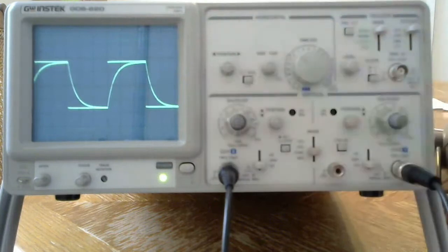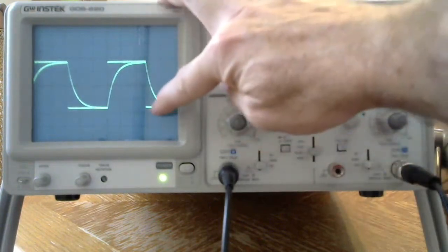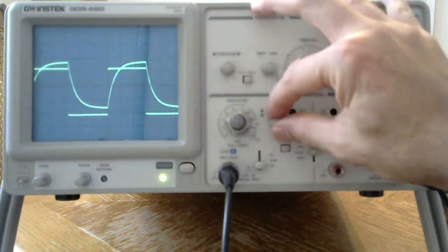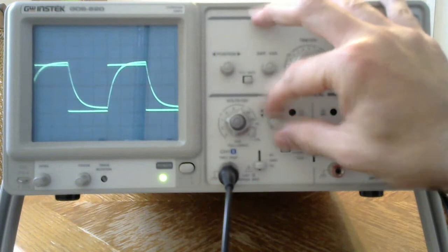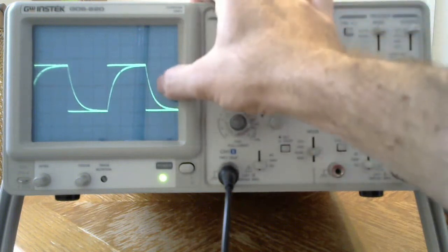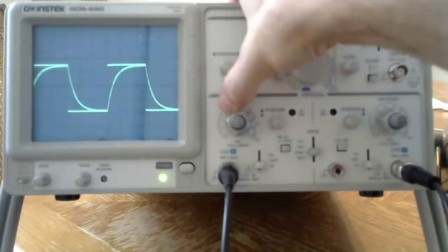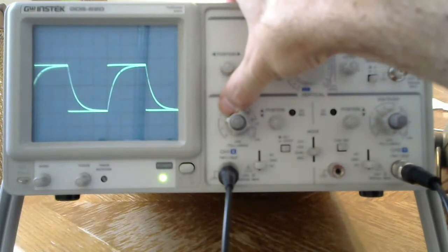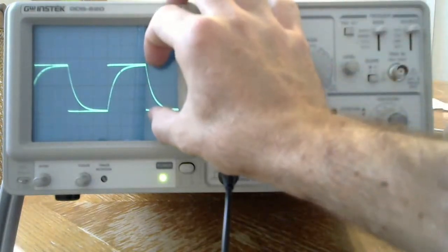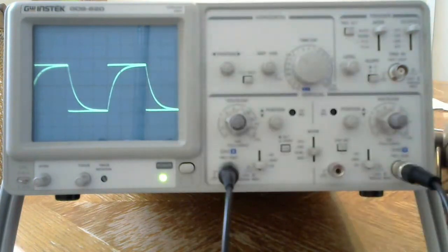Okay, so I'm going to set this back to 1 volt per division here and 1 volt per division here. So basically, right now from this point to this point, if I align these with the boxes so I can see exactly where they are, I'm reading 1 box, 2 boxes, 3.5 boxes. 3.5 boxes vertically is 3.5 volts. So this distance here vertically is 3.5 volts right now.